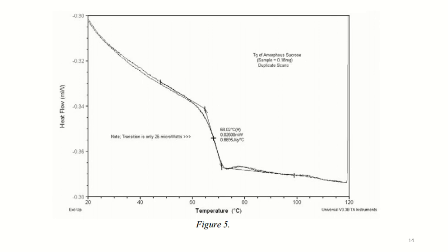Because this is a modulated differential scanning calorimetry experiment, the transitions are separated into reversing and non-reversing signals and can be more easily interpreted.